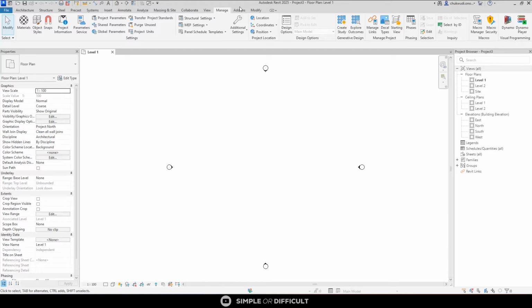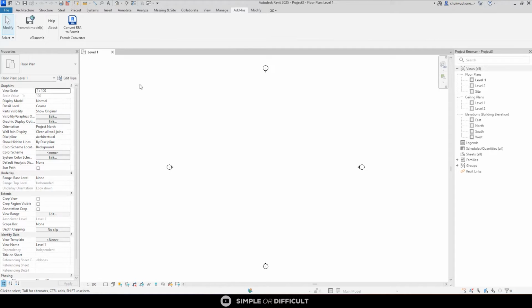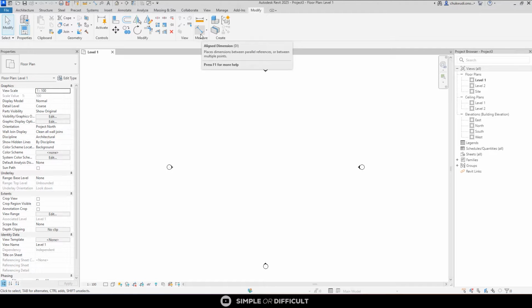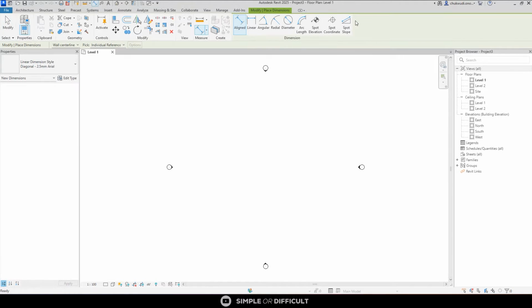Okay, so Add-ins: when you start adding plugins to your Revit, they are going to appear here. Some will even create tabs for themselves on your ribbon. Okay, Modify is what you use to edit further. Now, when I place a wall into this scene, I can use the tools on this Modify tab to edit it even more. You can also see the dimension. When I click it, it brings out other dimensions, then I will select the one I actually want.